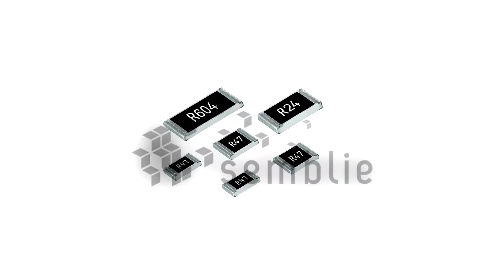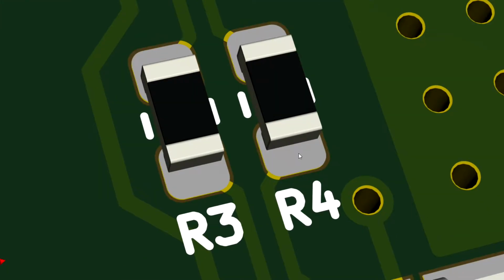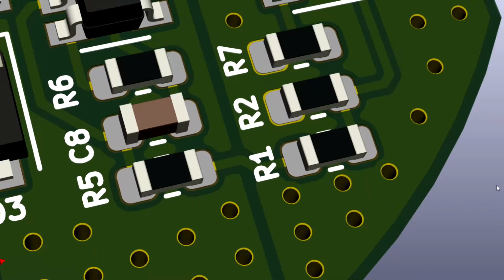SMT marking codes usually come with 3 or 4 digits. For both of them, the last number indicates how many zeros are being added to the first 2 digits. A 3-digit code has a tolerance of 5%. A resistor marked with a 4-digit code has 1% or less.